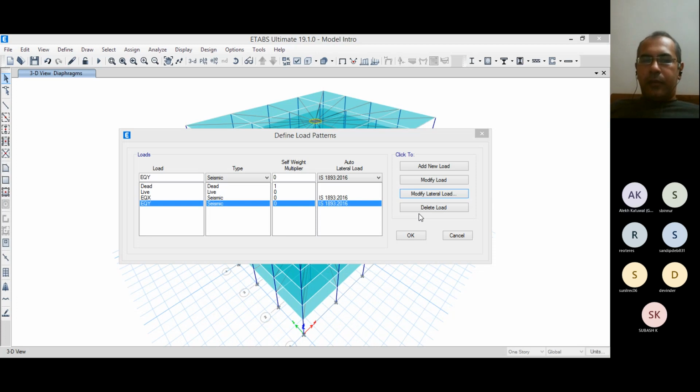Right now we have kept it simple. So basically on ground the building is there. We have not considered the basement. Once we add the basement, then our conditions will change. The height below the basement also will be considered. So your total height will be from top of the foundation. Always we consider the height of the building from top of the foundation to the roof level. So when there is a basement, then from top of the foundation to the top of the roof, that much height we need to consider.